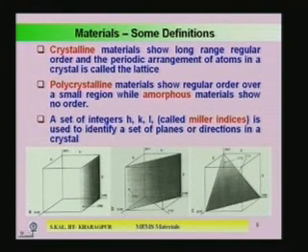On the other hand, in the amorphous, there is no regularity in the crystal lattice structure, it is highly irregular, and the atoms inside the crystal are placed in different directions. So, in a haphazard direction, so it is known as amorphous material. One example is, if you evaporate certain metal film on a single crystal silicon substrate, this film is an amorphous film.